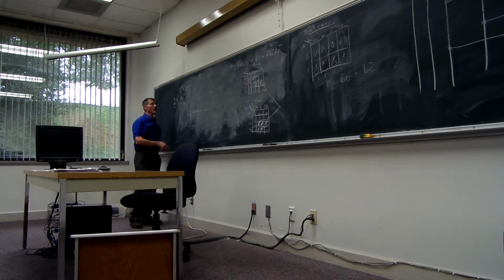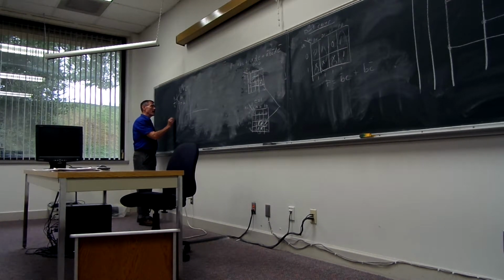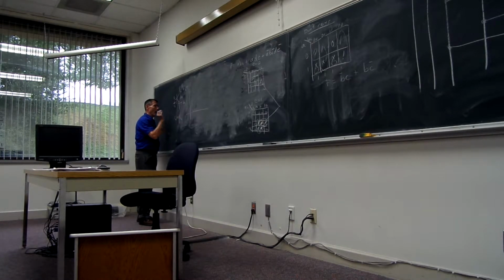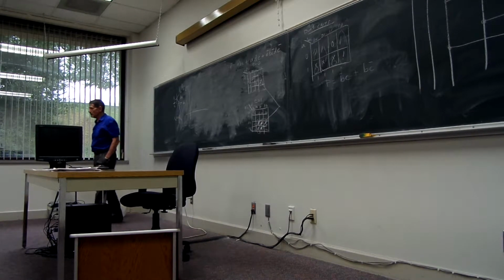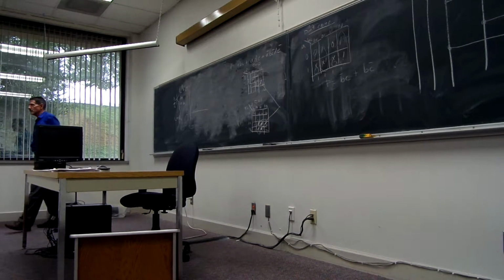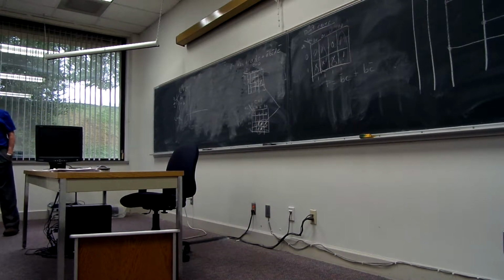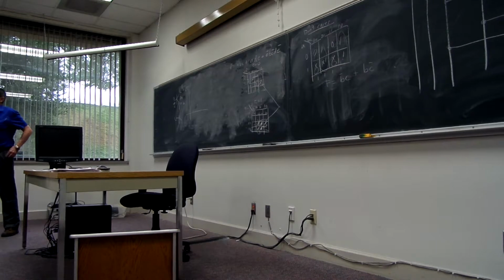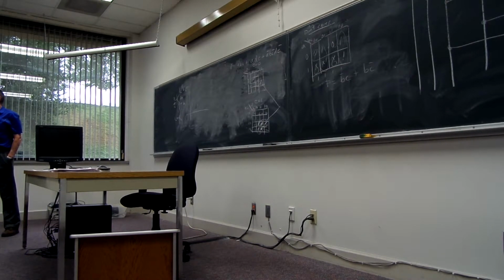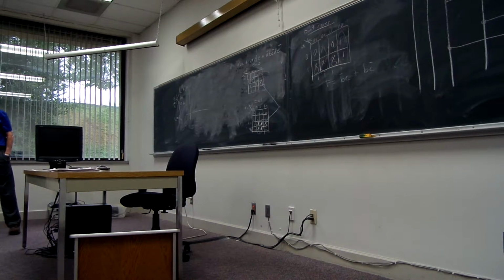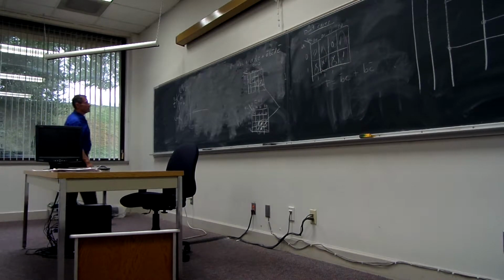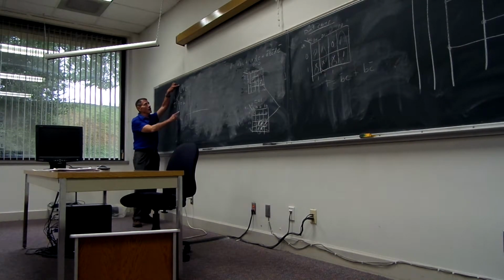So your transistor is basically a current amplifier. I know we like to talk about voltage amplification, but these BJTs are current amplifiers. We can fudge things in our analysis and assume that they're voltage amplifiers and keep our heads on straight, but they're really current amplifiers. You bias this so there's a large voltage here with respect to here.